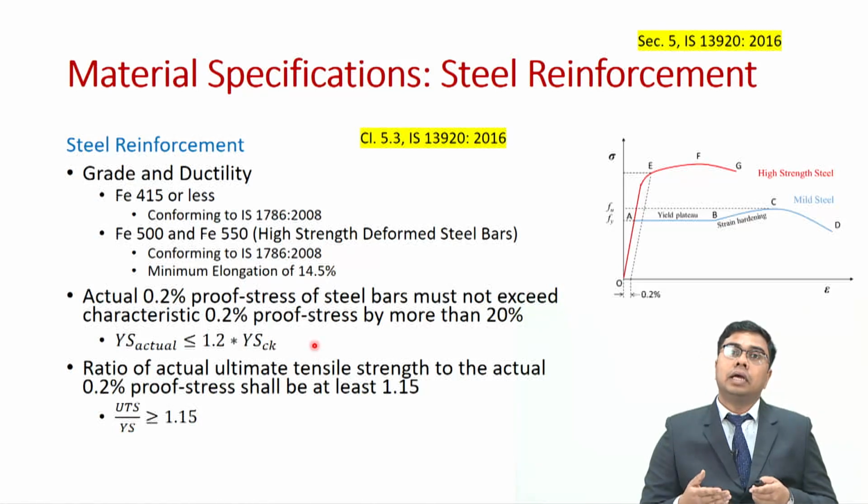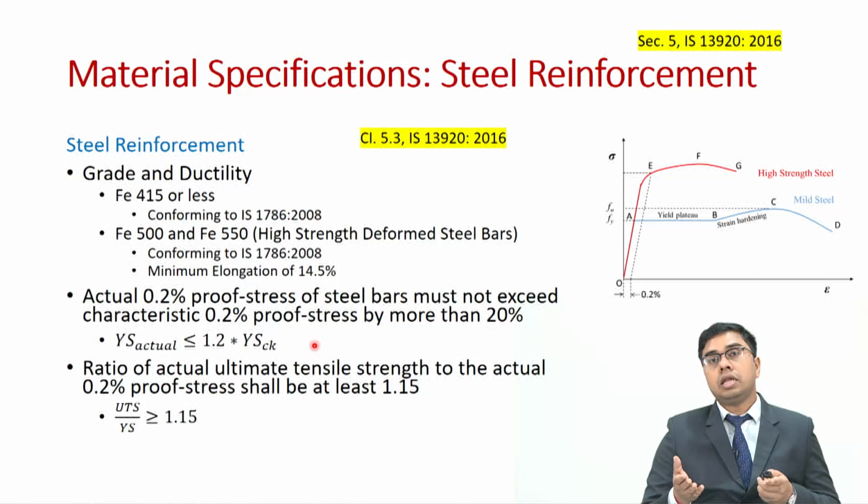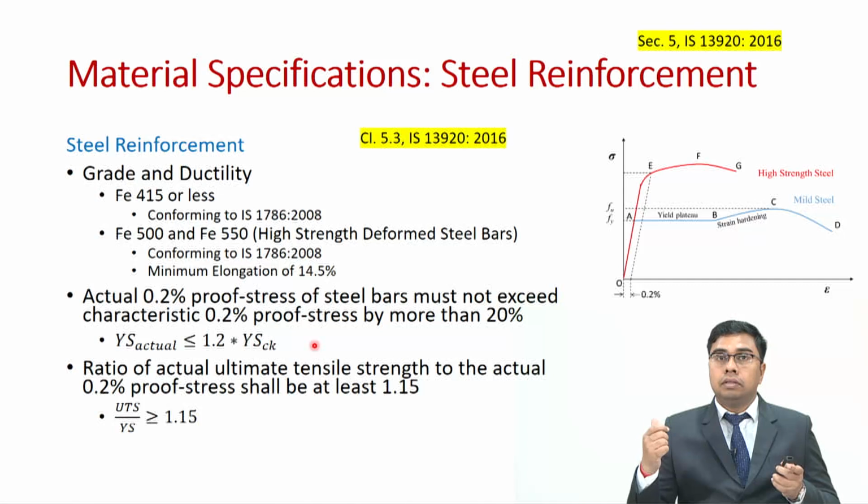If your ultimate moment carrying capacity of the beam increases, then the beam will find it difficult to develop plastic hinges, and if it finds it difficult to form plastic hinges and the column finds it easier to form plastic hinges, then in that case plastic hinges will get formed in the column, which will lead to an undesirable failure mode, that is, that will not be following our capacity based design of weak beam strong column hypothesis.